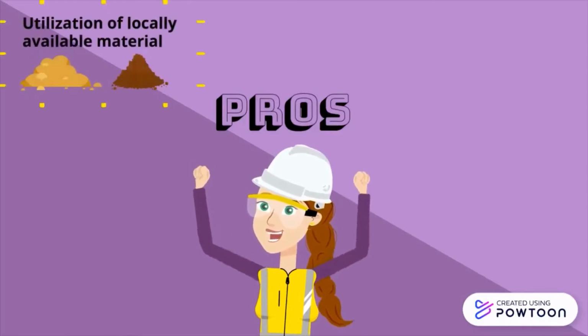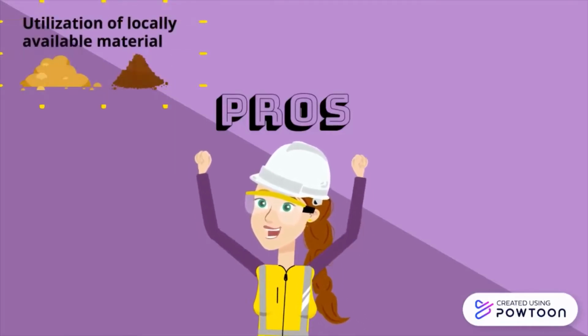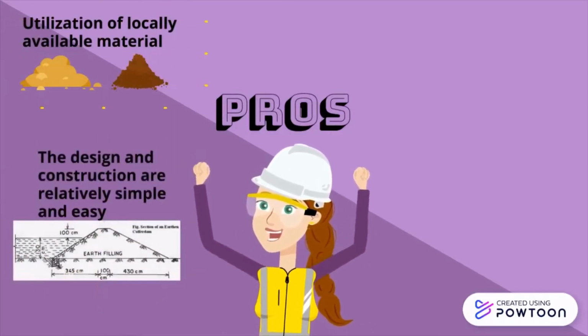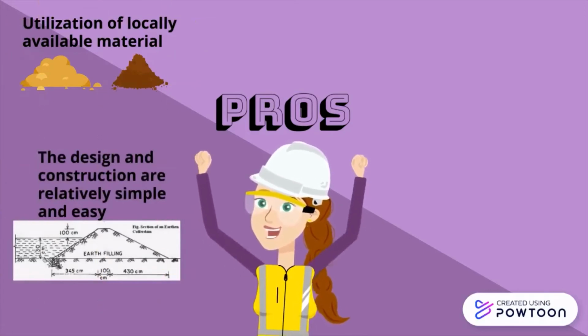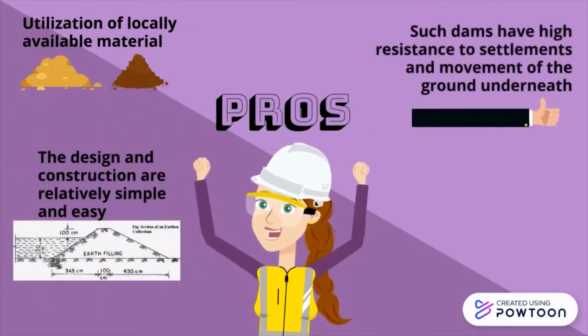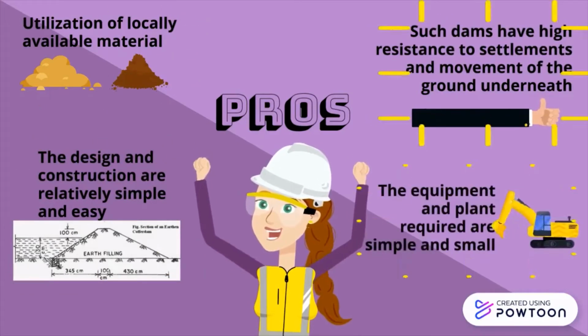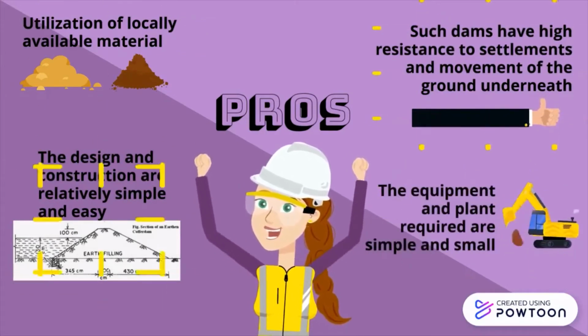First, the utilization of locally available materials. Second, the design and construction are relatively simple and easy. Third, such dams have high resistance to settlements and movement of the ground underneath. And lastly, the equipment and plant required are simple and small.